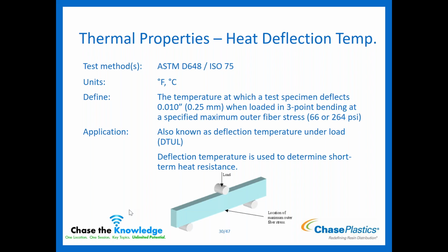Now, if they come to me and say it's only going to maybe see 100 C, I can go, for short term, this is definitely going to pass that. It's going to be no problem. So just note it's a short term test, it's not a long term one. Also, if I'm using it consistently at a certain temperature, at 201 C, it's something we need to look at maybe outside of HDT. It's just a quick little indicator: this is going to deflect at this temperature, so be aware of that.